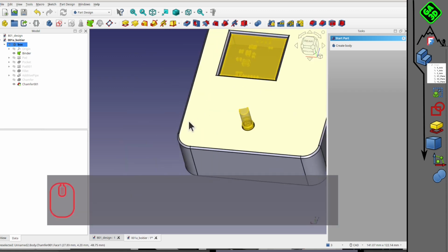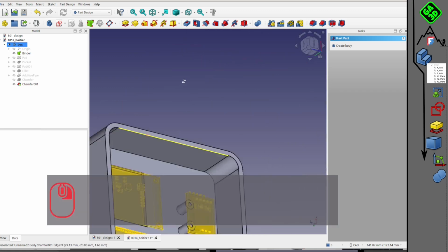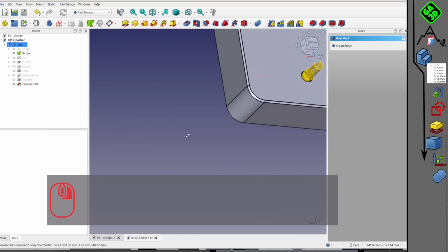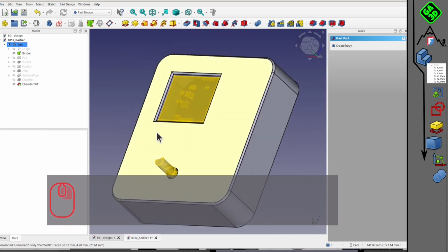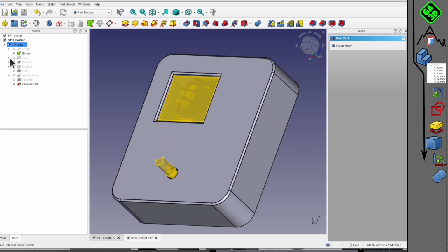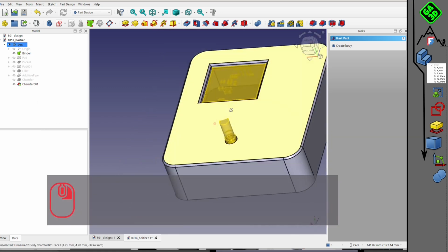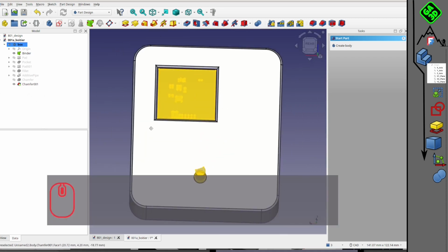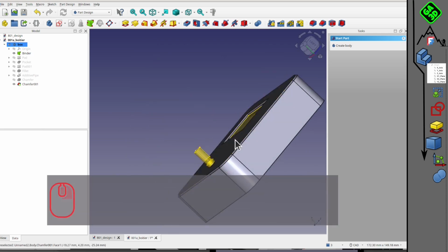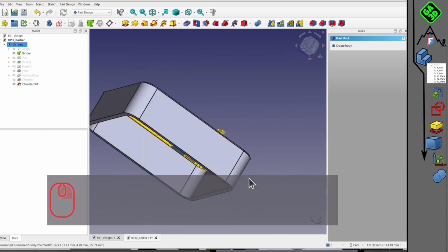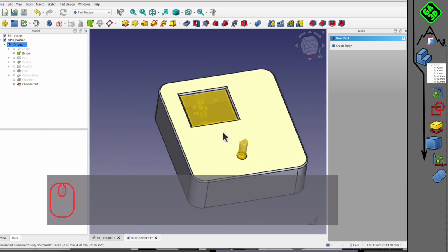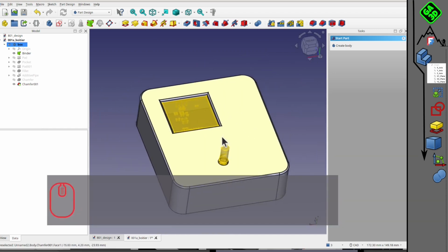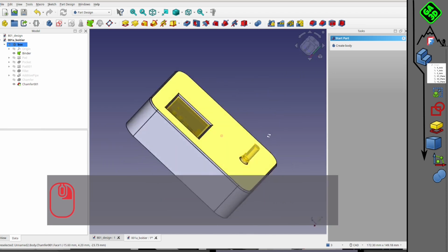After that, the process is the same as the part alone. So it's a sketch, a volume creation, material removals, screw passage, anything you want. And always at the end, the chamfers, the fillets for the sketch. So that's the second case. I'd say it's the middle part. So here it was already a kind of mini project, in fact, but it's something quite common.